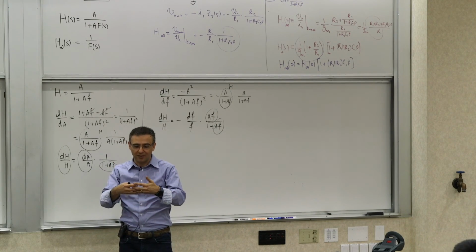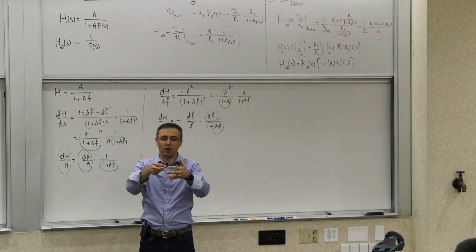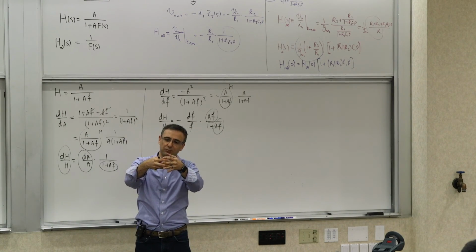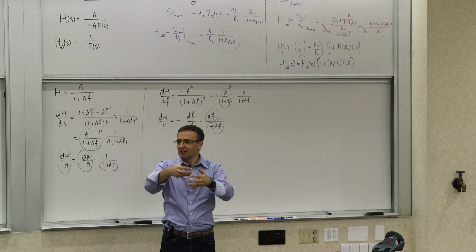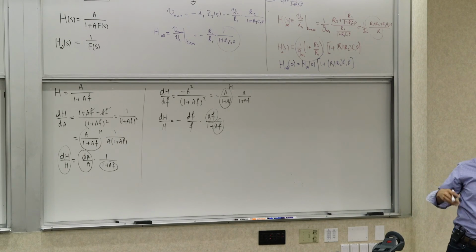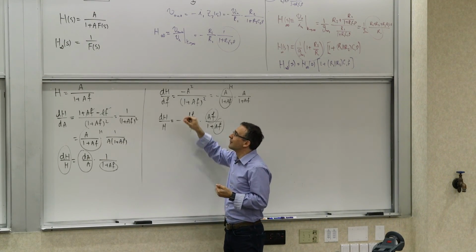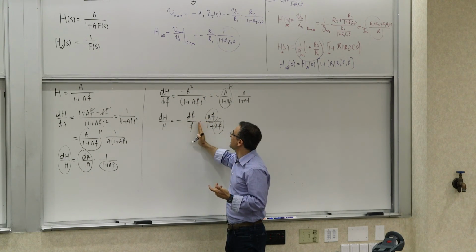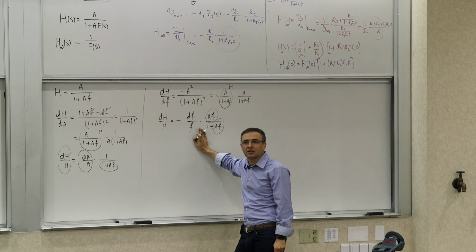If it's on chip, you want to make sure they have the least amount of process variation. So you take one finger, part of this resistor is here, part of the other resistor is here, and then you interleave them so the variations average out. We talked about other techniques like common centroid. Depending on how accurately you need something to be, how repeatable it needs to be, you need to be careful because there is no desensitization to variations in the feedback network.